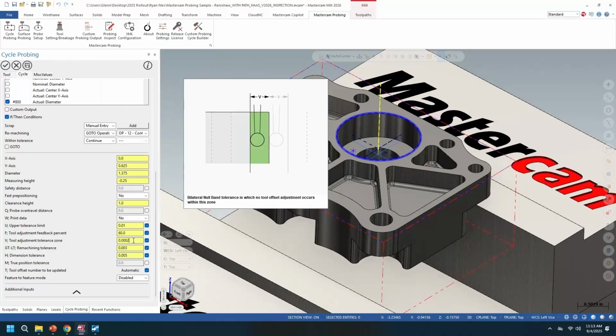If it's within two tenths, I don't necessarily need to chase the tenths on my tool and keep updating part after part. If it's within maybe a couple tenths, subject to the part and material, then maybe I don't care about updating the tool. I only want to update if it's outside of this area but underneath this area, more or less.